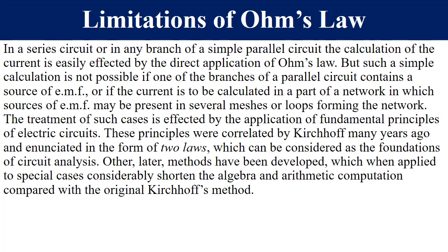We use Ohm's law to solve simple circuits, especially those with one source of e.m.f. Ohm's law cannot be used to solve circuits whereby we've got two or more sources of e.m.f. or current sources. Kirchhoff's voltage law as well as Kirchhoff's current law are used to overcome the limitations of Ohm's law. Hence, the reason for this video presentation on Kirchhoff's two laws.